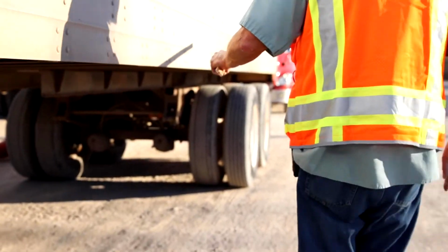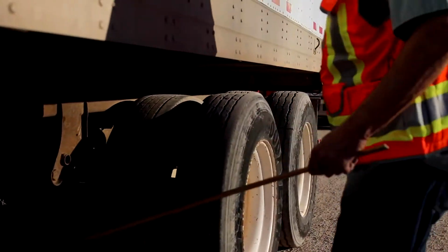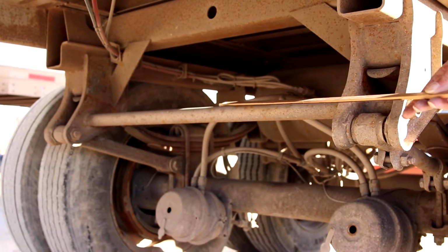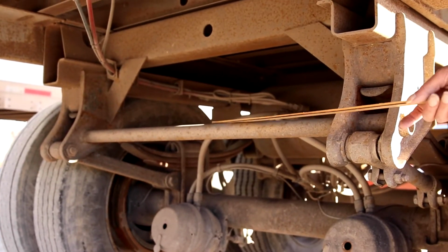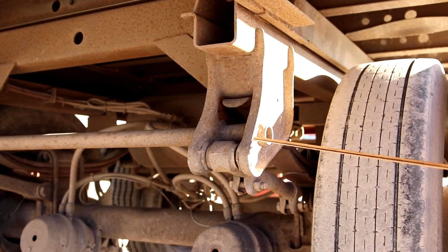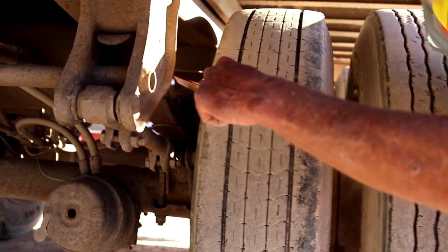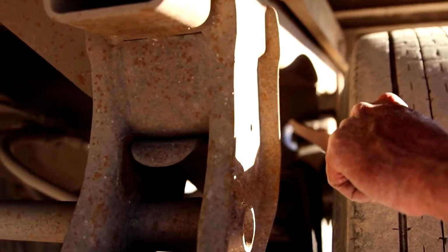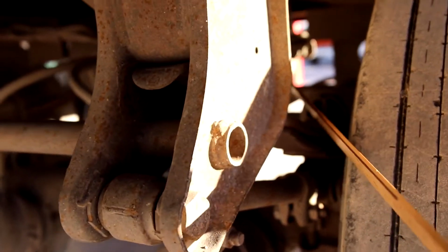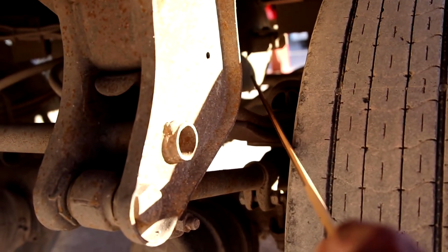Moving on back again. Checking the sidewalls of your truck. Then, coming underneath, this is a torque bar on your rear suspension of your trailer. This is your front spring mount. You'll also have a rear spring mount towards the rear of the trailer. You're also going to have another middle mount. That's held in place with two U-bolts and 4 nuts.